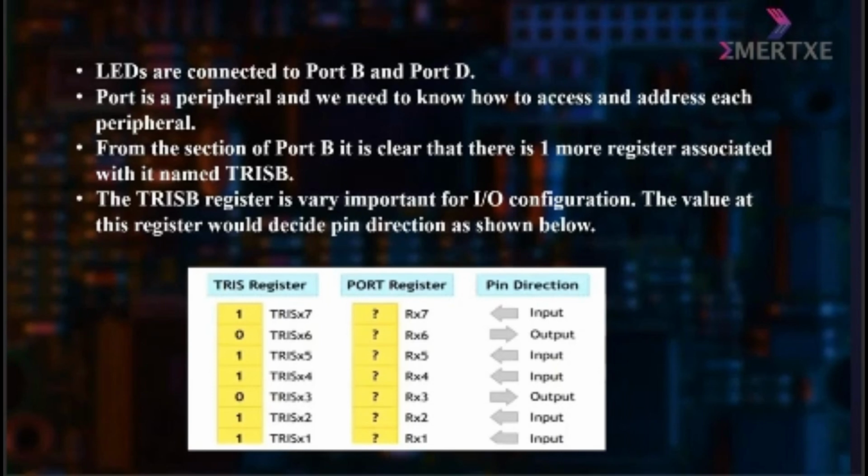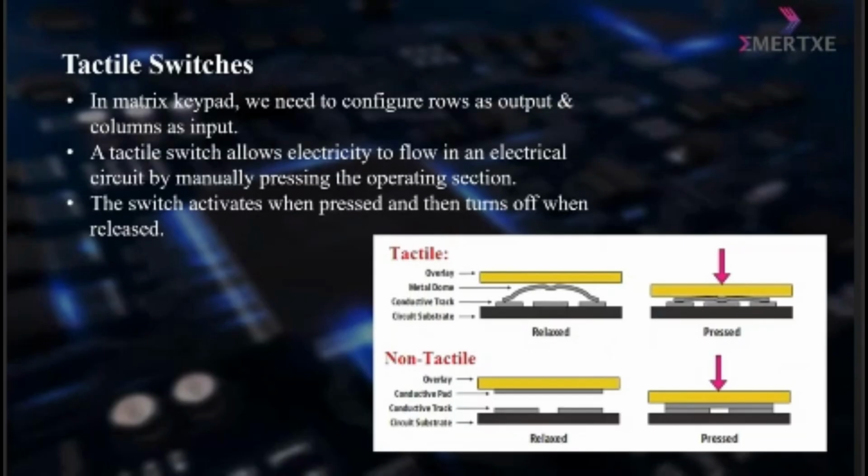The TRISB register is very important for input-output configuration. The value of this register decides the pin direction, as shown below. And now, tactile switches. In a matrix keypad, we need to configure rows as output and columns as input.